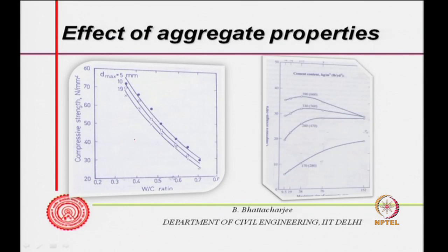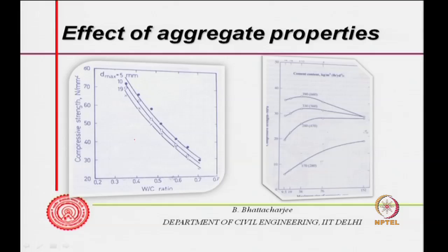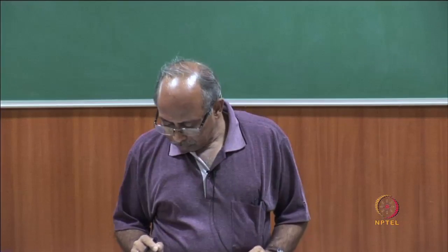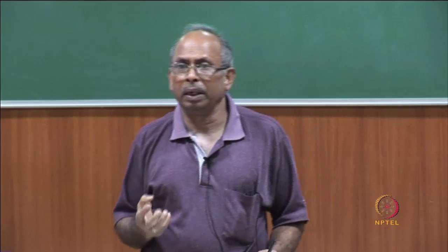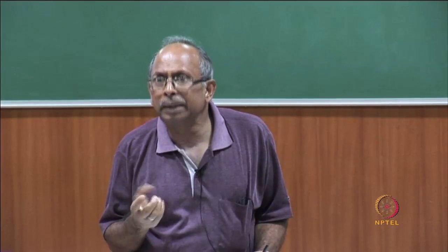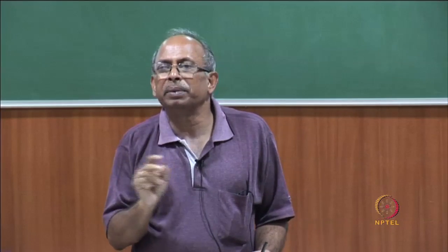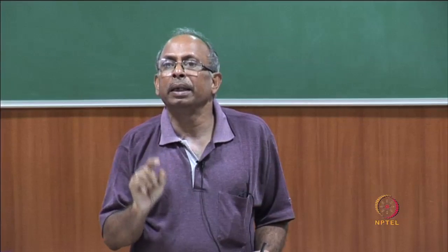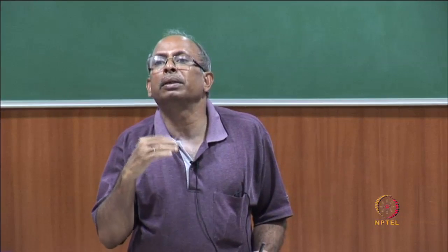So, this curve is lower, and it has actually been observed that MSA governs the strength. How does it govern the strength? You see, it has two kinds of effect. The larger the MSA, the stress around the maximum size of the aggregate is going to be higher.